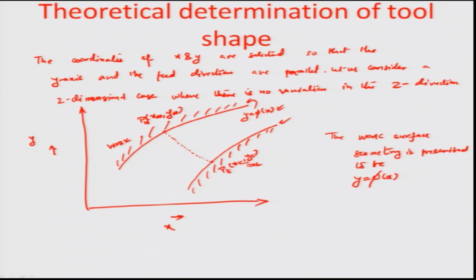Further, this is a case where the work is actually moving at an inclination angle theta with respect to the tool surface. So, let us say if the tool surface goes like this is how the workpiece is going to move, and if I were to just connect the surface P t with respect to the perpendicular, there is a point here which it makes, we call this the point A, whereas this origin is O. Further, the gap between the 2 points opposite to each other in a perpendicular direction is given by the equilibrium gap G e.